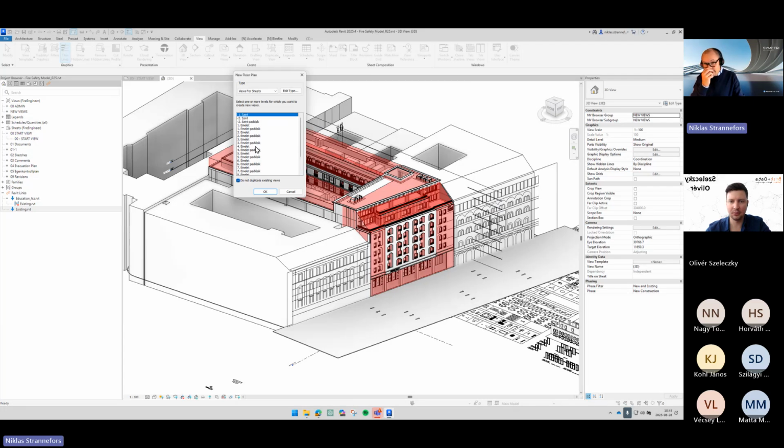But what I just want to show here, we're going to go back a few times. Here we have all the levels that we copied. In the very top here, I have different view types for floor plan. There's nothing special about these floor plans. What I've done here is I connected a view template, meaning there's a way I want them to look to different floor plans. Instead of copying a floor plan and changing a view template, you could do that as well.